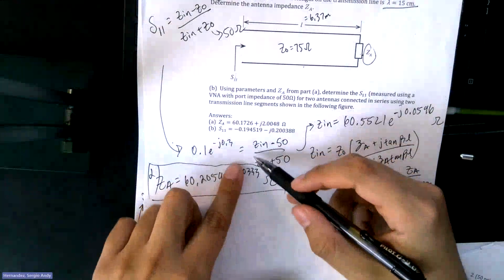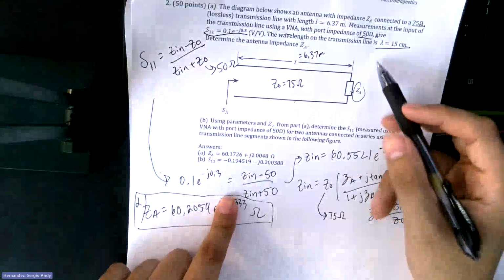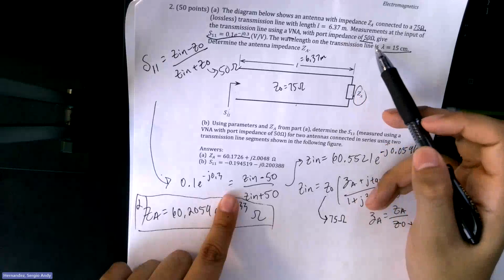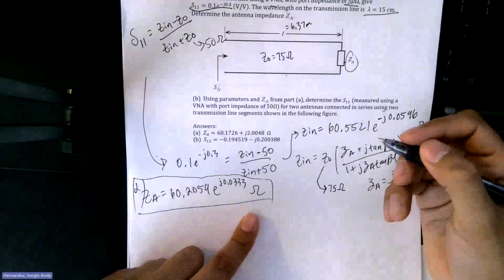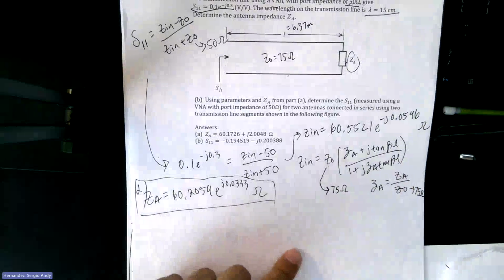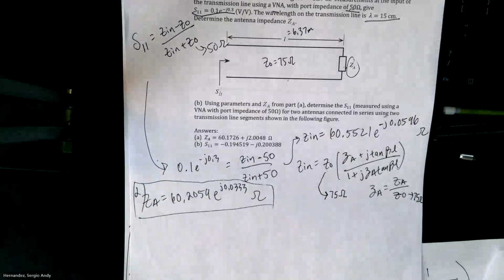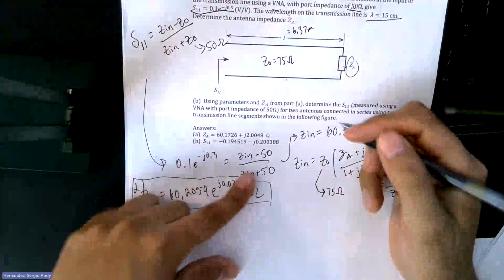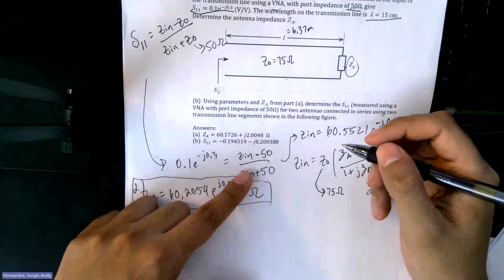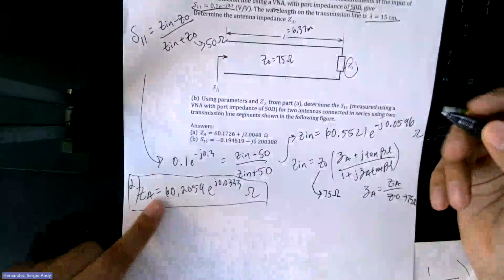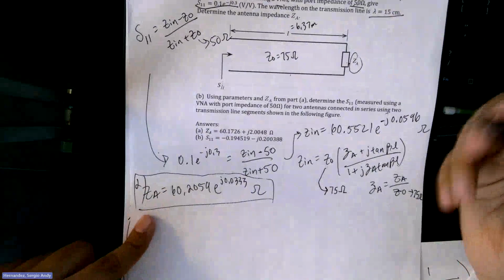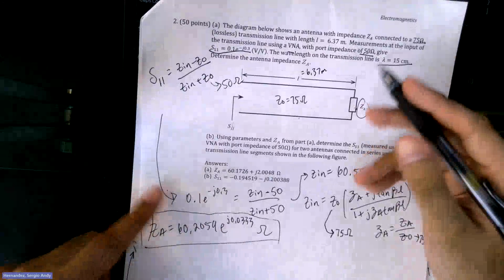When instead, right off the bat, you're dealing with the VNA measurement, which tells you it has a port impedance of 50 ohms. And if he doesn't specify anything like he did in the previous problem, assume the characteristic impedance of the transmission line equals the port impedance. So 50 ohms. If he doesn't tell you port impedance, 50 ohms.